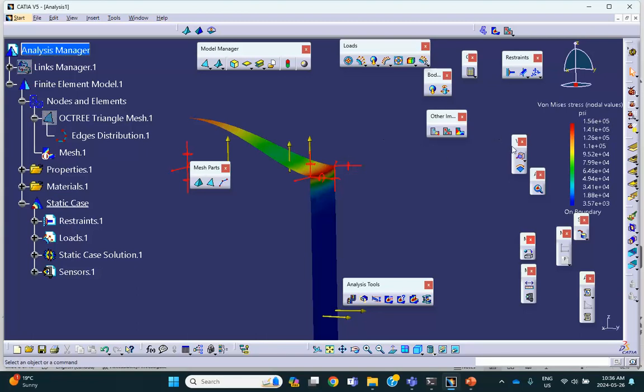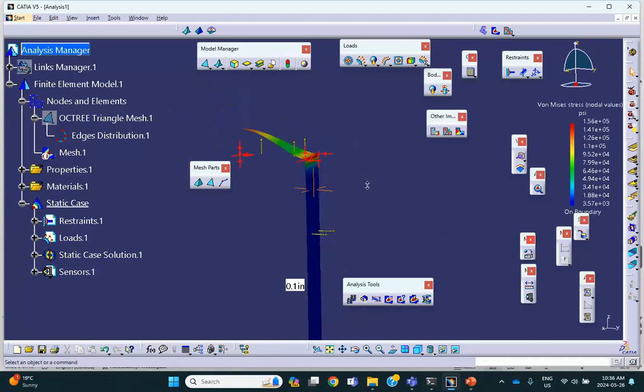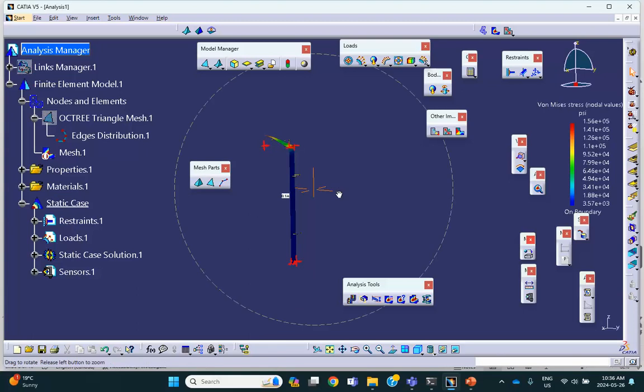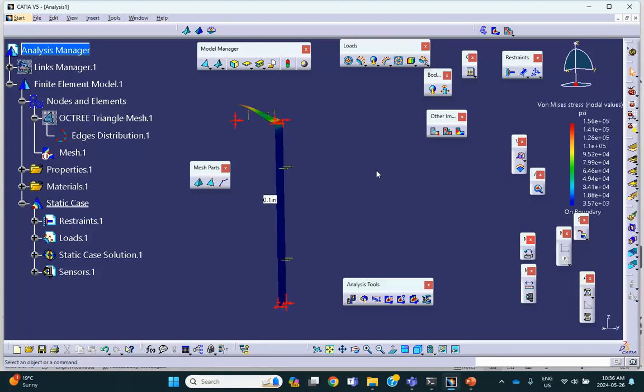Assuming that we trust these, because we have not done a mesh convergence study, I don't know. What I'm saying is that this is 150,000 psi. Yield strength for structural steel is 30,000 psi. Now keep in mind that if these are, just hypothetically, containers that carry hydrogen for fuel cells and things like that, they're not made of structural steel that you use for I-beams and buildings. They are high strength steel, and so that depends on your situation.